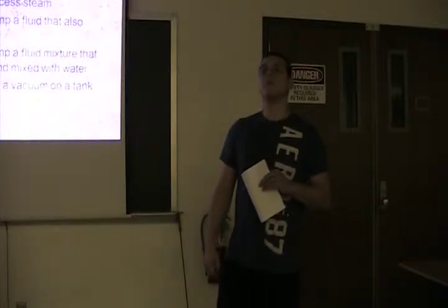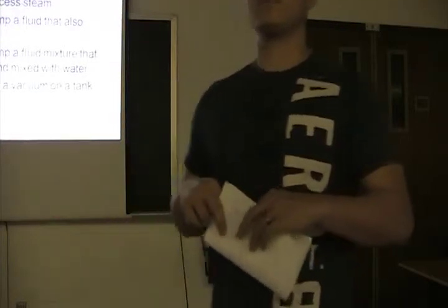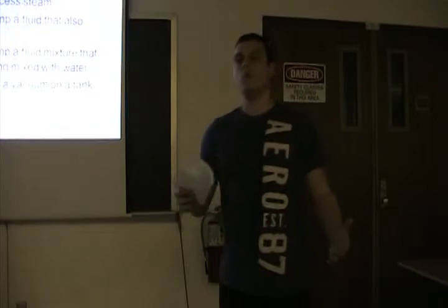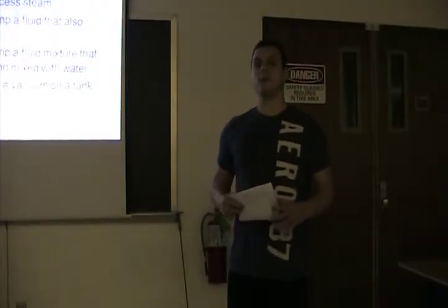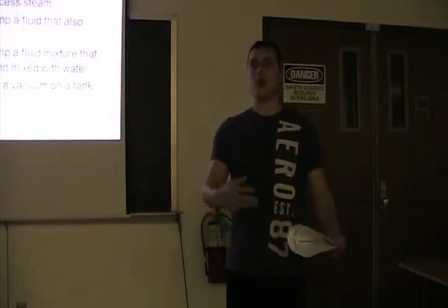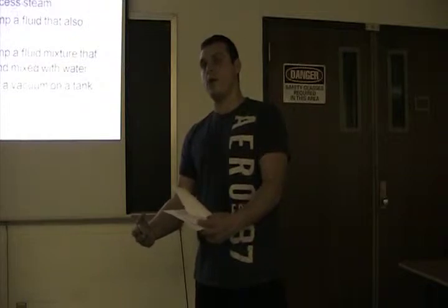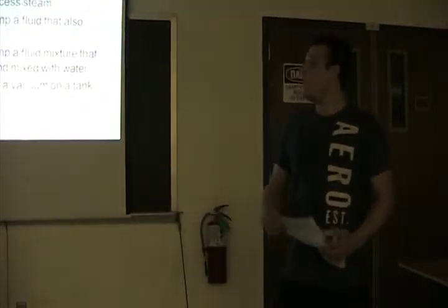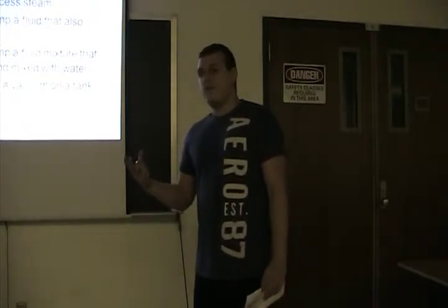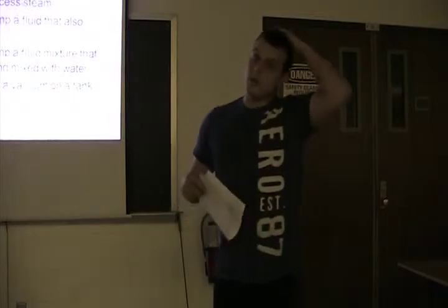What do you think would be more efficient to use it as a pump or as a heat stream? Well, it really depends on what you're trying to use it for and why you are using it as that application. Does your process have excess steam, so you're using a byproduct to use it as a pump, and you want your wastewater to be heated, or are you just trying to pump something? Also depends on the quality. So the efficiency is going to vary with how fast the steam's going through. So really, the operation that you're trying to perform it on.